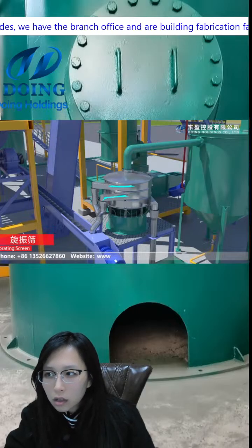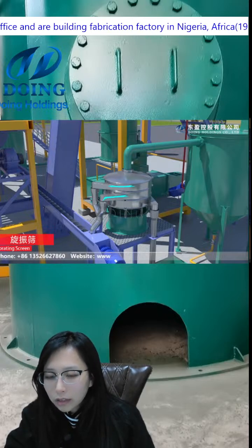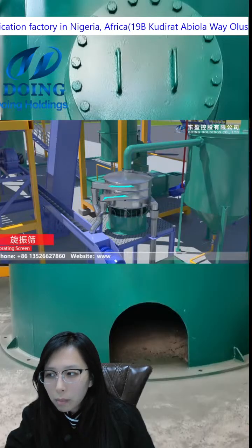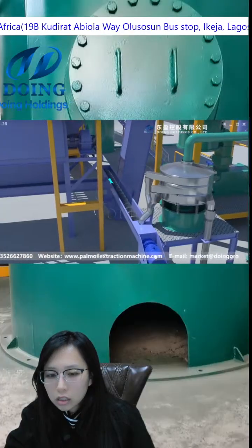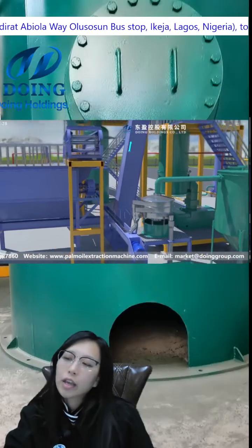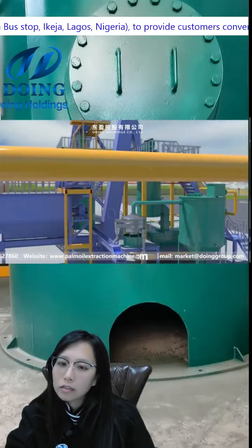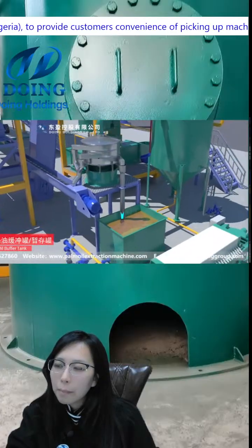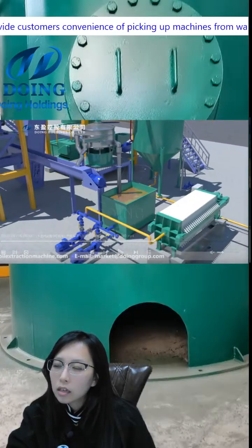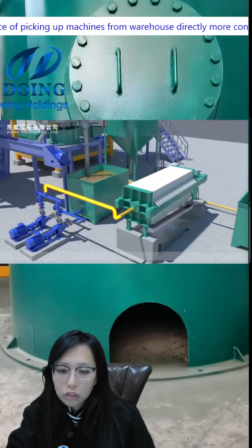But for these impurities, it may be that some can't get enough pressure. Yes, it may still contain some palm oil. So after this, we will collect this material to enter the pressure again. We can see this process collected to the digester. Yes, to digest again, and then to press again. But some cleaner palm oil will enter the next section. Yes, to our filter system.